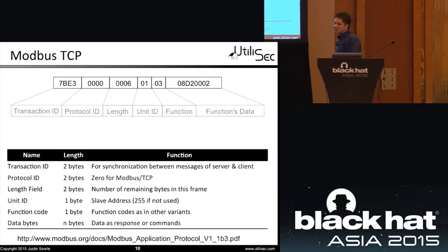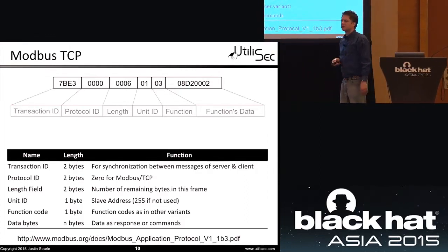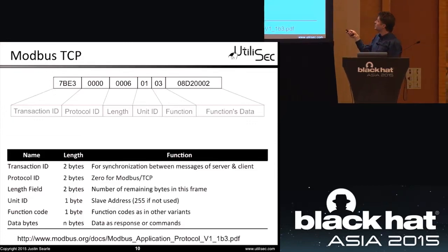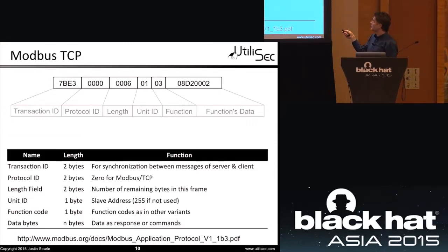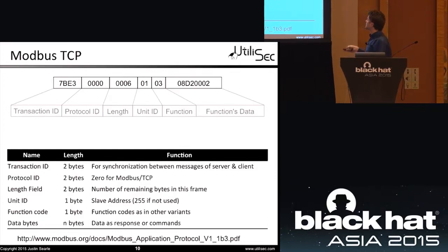When we talk about the TCP/IP version of Modbus, there are 2 serial versions, but we're talking about the TCP version. The TCP version of Modbus has only one version, version 0, so you should never see anything but zeros in that section. Okay? The length. The length is an identifier saying how much data comes from this point on inside of the packet. Then we have a unit ID, so actually 6 bytes.